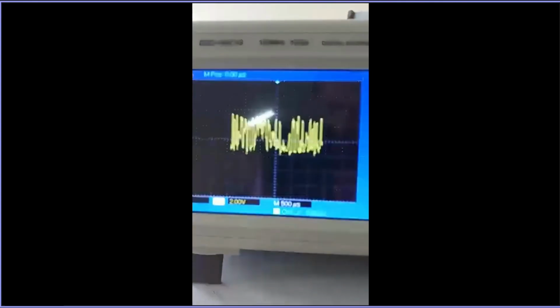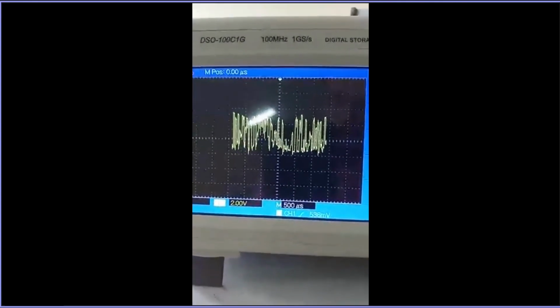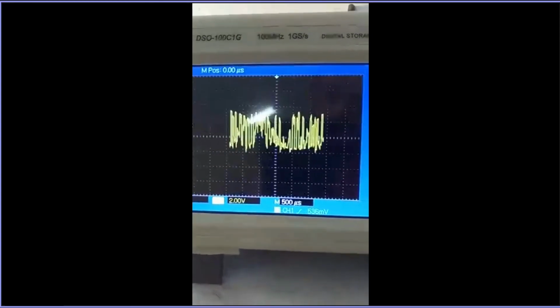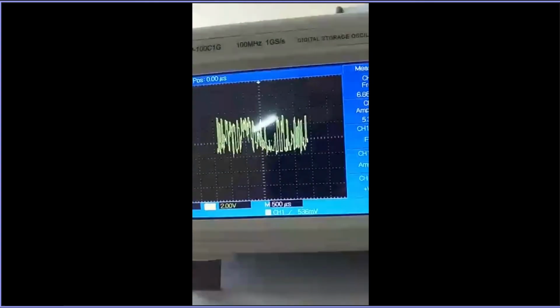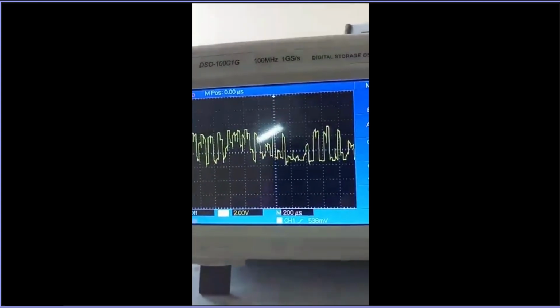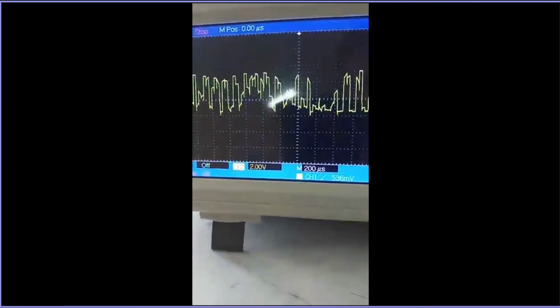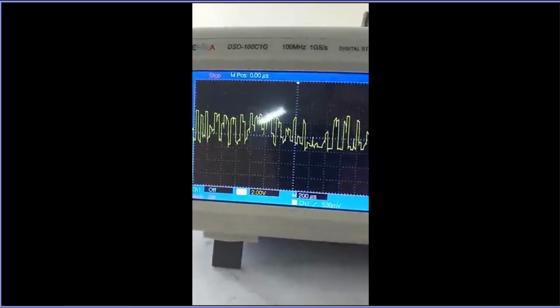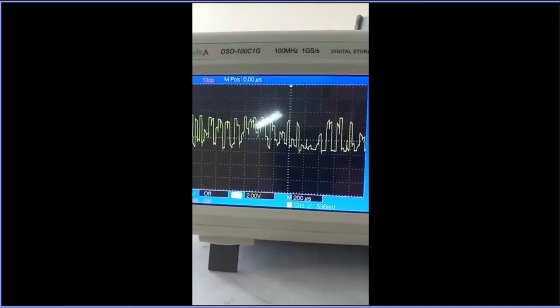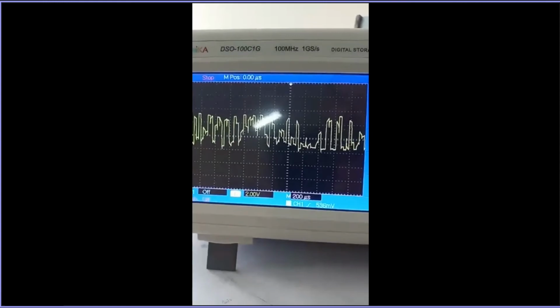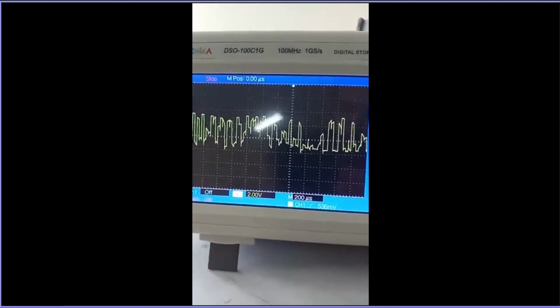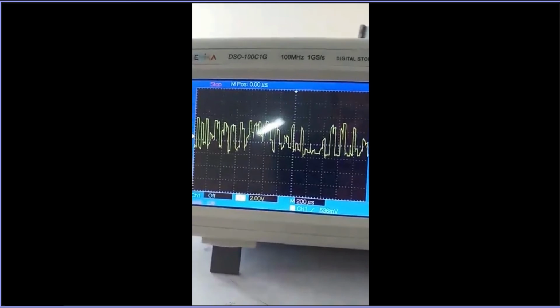Yes, that's fine. This particular slot, if you see, is carrying the output of all the 4 inputs you have seen, channel number 0, 1, 2, 3. All the inputs are here in the combined form. Right, so this is the magnified look. This is the output of the multiplexer, where on the time slot basis we have channel number 0 output, then channel number 1 output, then 2, and then 3. Okay, and this is the input for the demultiplexer.